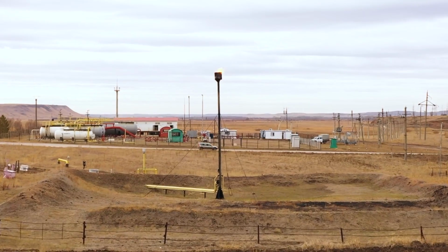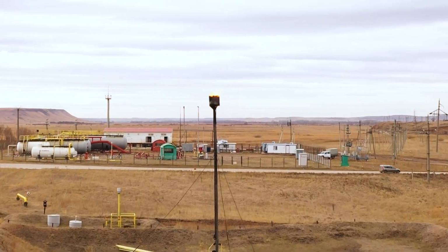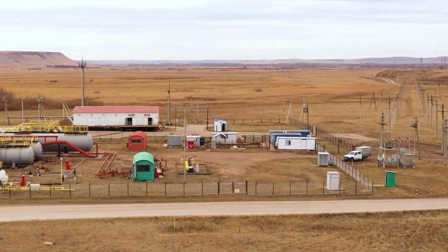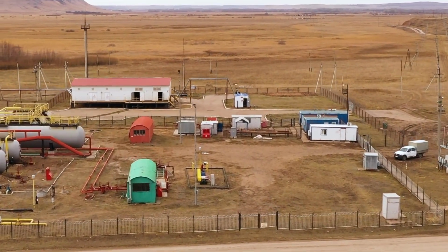That last part is important because the supervisory control level includes edge computing solutions as well. While that oil and gas company could run Ignition's Perspective module on a mobile device at these types of remote locations, that still requires an operator. Luckily, this is exactly what Ignition Edge was designed for. They could implement Ignition Edge IoT to easily bridge device data between remote sites and their central control room. And if they want to maintain that same level of visualization at the network edge, they could utilize Ignition Edge Panel as well to turn any screen into an IoT-enabled HMI.